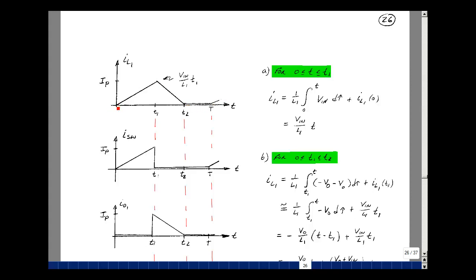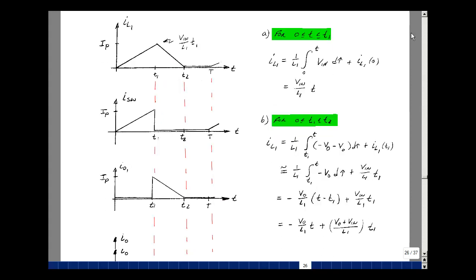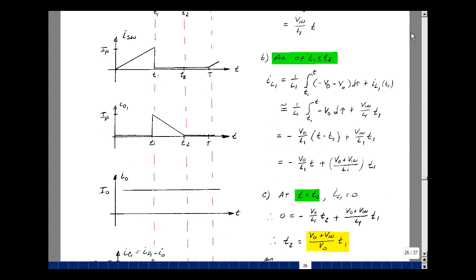So we come back over here, we have 0 current in the inductor in steady state. Now we close the switch. We begin to integrate that voltage. The switch is closed, so the current's going to follow the same pattern. At the same time, the diode is off. We're assuming that we've reached steady state, so there's a voltage across the load that's fairly constant with a little bit of ripple in it. Current on the average, again, this is shown in the opposite direction of our previous case because it's going to be a negative output voltage, is fairly constant. So I just call that capital I of 0 for its average value.